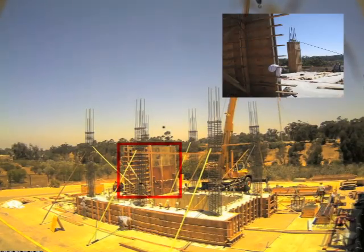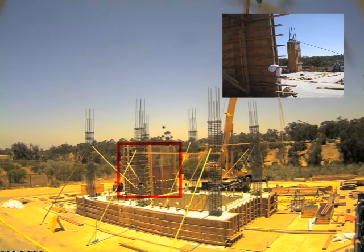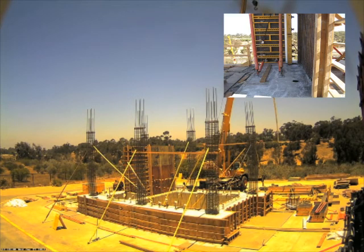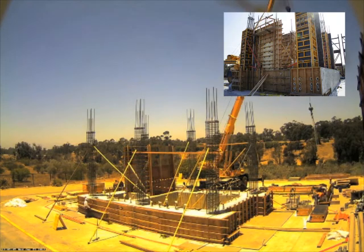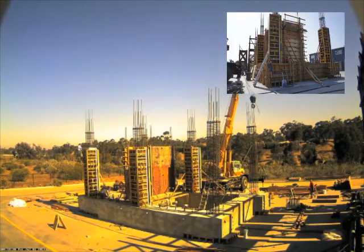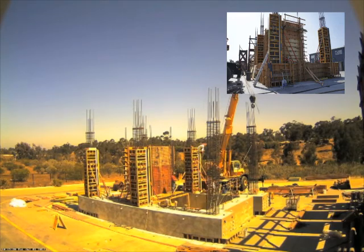The next phase of the construction process for this building was to build the shear wall for the elevator shaft. Shear walls resist lateral forces, mainly caused by seismic and wind loads. The formwork used for construction of walls depends on how many sides of the wall require forms, either a single face of formwork or a double face. For this project, the elevator shaft shear walls required double face formwork. Shear wall forms were installed similar to the formwork described earlier for the foundation.